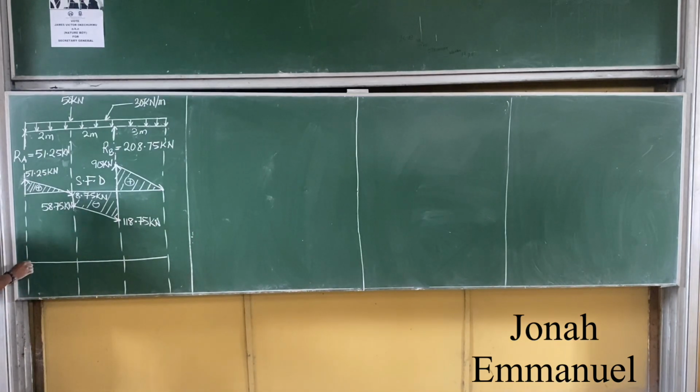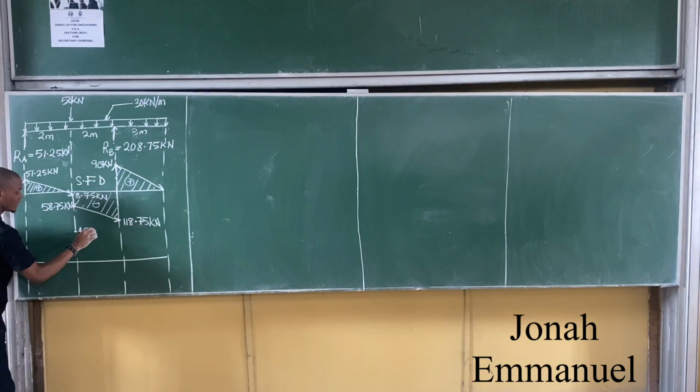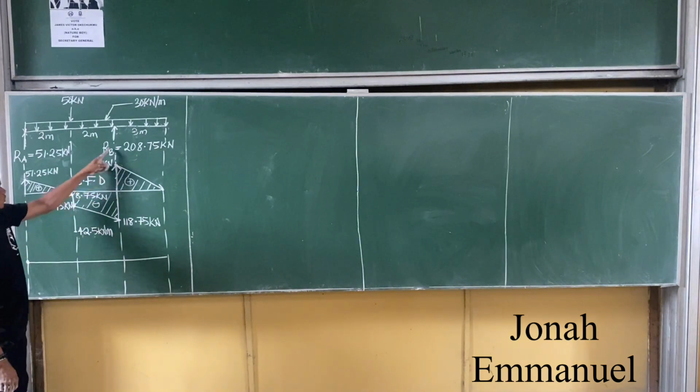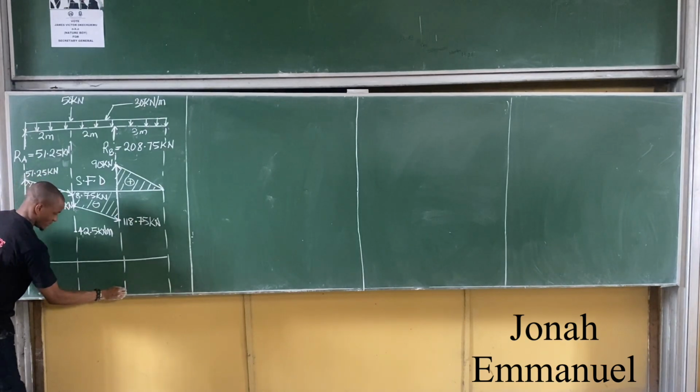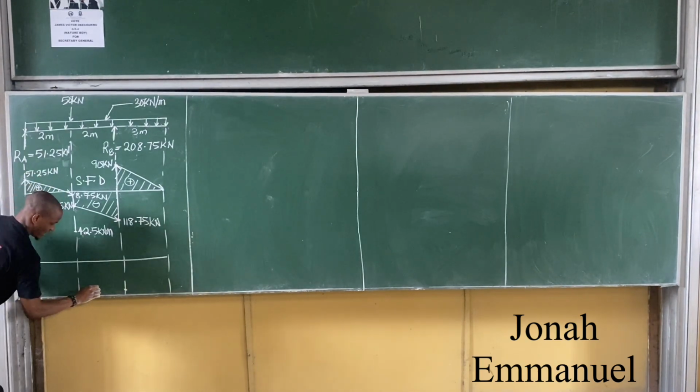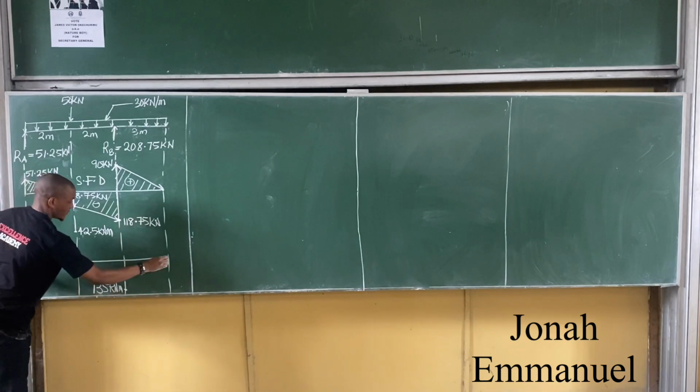Now let's get bending moment, please. At x equal to 0, what's the value there? Bending moment is 0. At x equal to 2, what's the value there? Yeah, that gives you what there? 42.5 kilonewton meters. Okay. At x equal to 4, what's the value? Minus 1.5. That will be down that bit. Okay. Minus 135 only. So it becomes 135 kilonewton meter. Next up, 0.